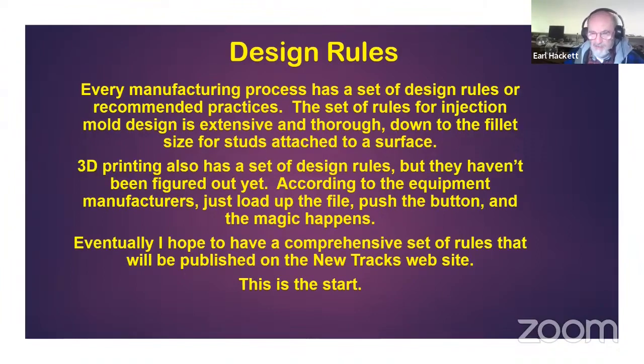And these are design rules that specify, for example, you'll often see on a model a plastic surface with a stud stuck to it that you run a screw into to hold it onto something. Well, the design rules will go so far as to tell you what the radius of the fillet should be at the bottom of that stub, so you don't disturb the surface that it's stuck to.